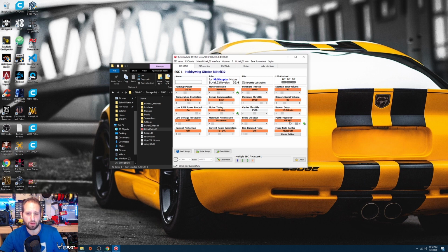I was mentioning before, I don't think I actually explained this before, but PWM frequency can help provide smoother motors and also a little more responsive motors as well. But the big takeaway is that it's pretty much providing more PWM pulses to the motors, and it's able to run them a lot more efficiently. So if you are running BLHeli32 ESCs, this will be at 24 kilohertz. So make sure that you are putting this at 48 kilohertz as well.